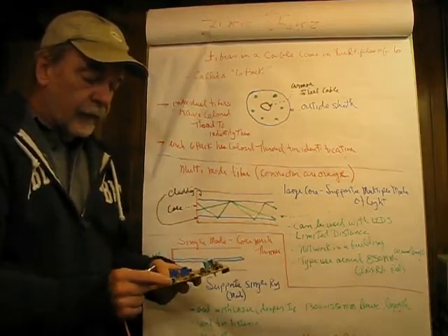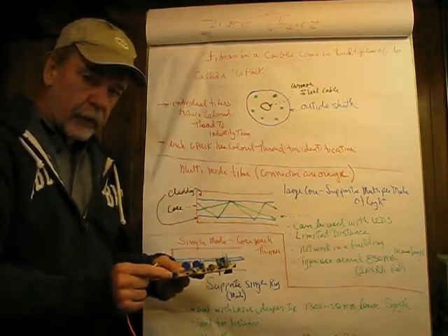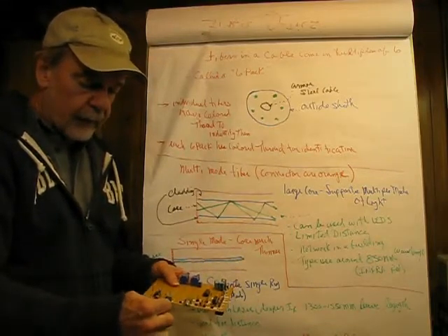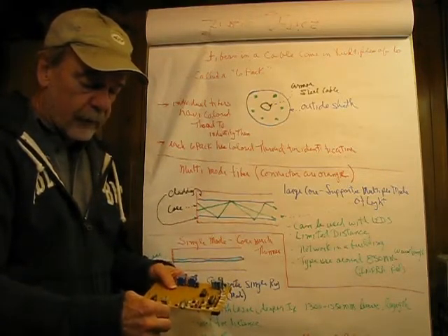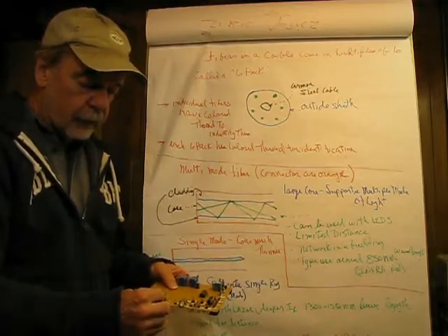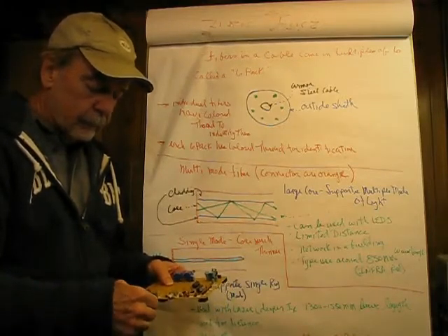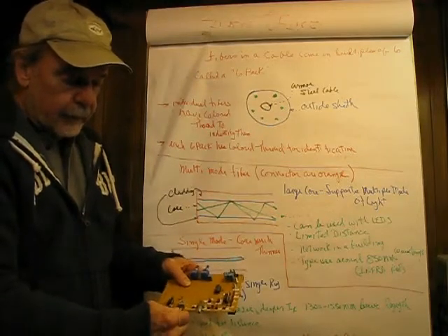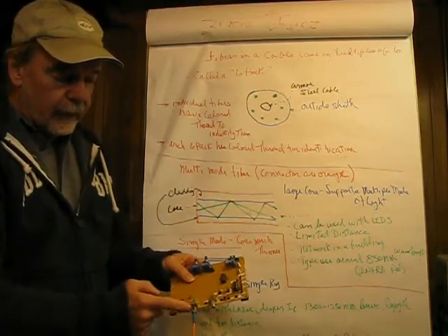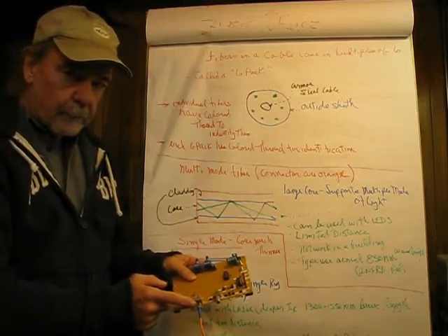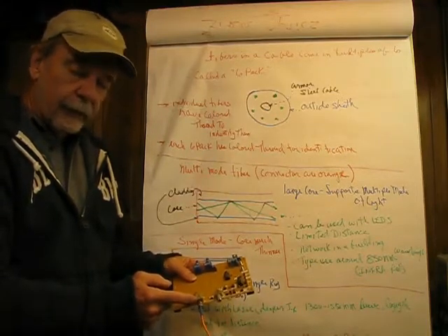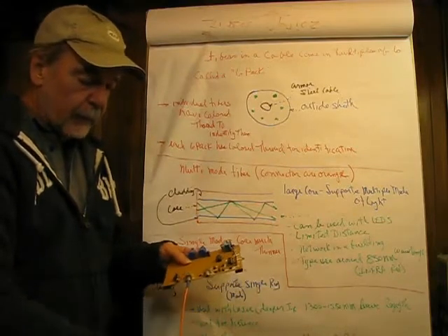Now, cleaning out the inside of this is done with compressed air, wearing safety glasses, of course. So this attaches kind of like a BNC connector. You have to rotate it to pick up the slot. There we go. Then once you get that, you push it in and twist it, and then it locks in place. It's spring loaded, so that this is held as close to the light emitting diode or the photodetector as possible.